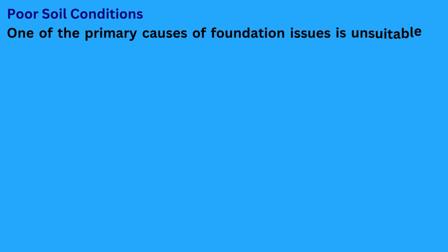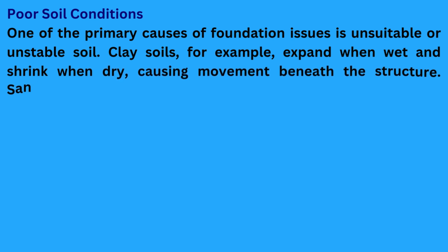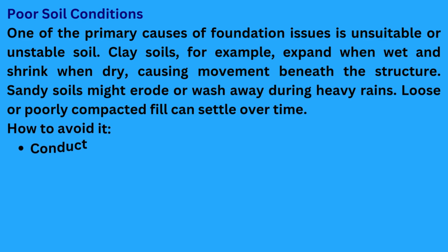Poor soil conditions. One of the primary causes of foundation issues is unsuitable or unstable soil. Clay soils, for example, expand when wet and shrink when dry, causing movement beneath the structure. Sandy soils might erode or wash away during heavy rains. Loose or poorly compacted fill can settle over time.